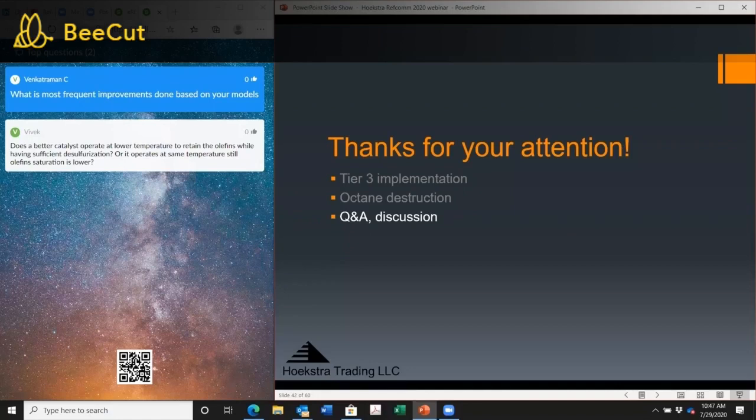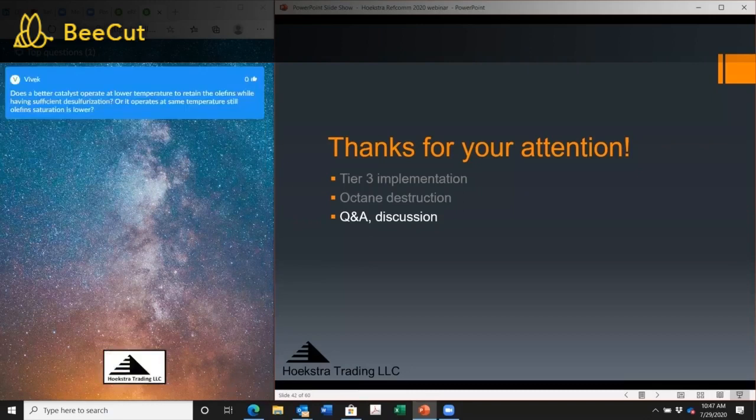Also the sulfur speciation, which I didn't talk about. When you are getting down to 10 ppm sulfur, the sulfur speciation tells you exactly what sulfur compounds are the ones you want to get out. And a lot of units have splitters, and you want to be able to optimize how much light naphtha you take out.